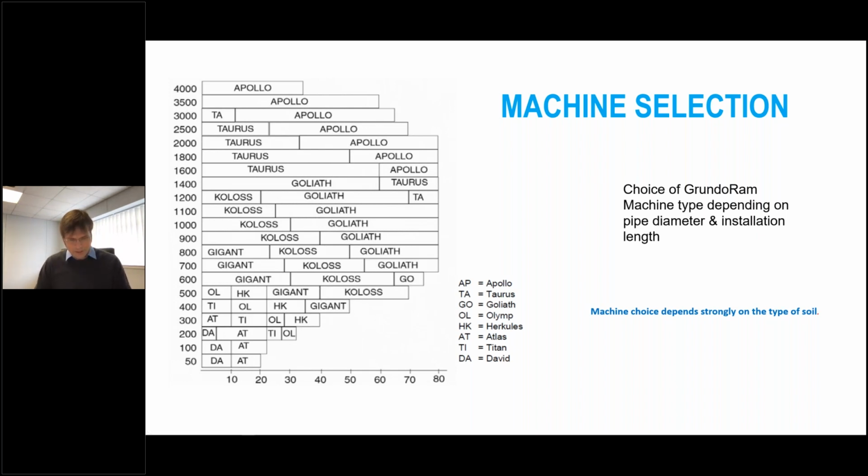And in reality, sometimes you look to choose the right rammer for the job, and you end up being on a borderline. My suggestion would be, if you are unsure or you know that you've got tougher ground conditions, always go for the bigger rammer. If in doubt, go a little larger.